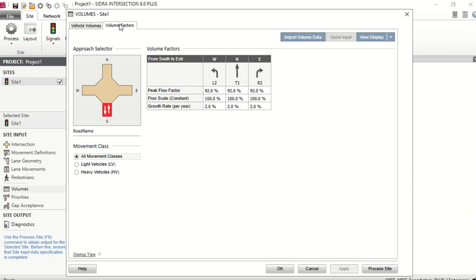And then we have the yearly growth rate. Okay, it will only matter if you are doing the analysis for like after 20 years, 30 years. You can ask the software, okay, do the analysis for me, what will happen after 20 years, 30 years. Only then the growth factor is important. Otherwise, if you are just doing the analysis one time, it doesn't matter. Whatever the volume you are putting now, it will just take this value and calculate the answers. That's it. Okay, so growth factor is only applicable when you are doing it for future growth or future analysis. Okay.